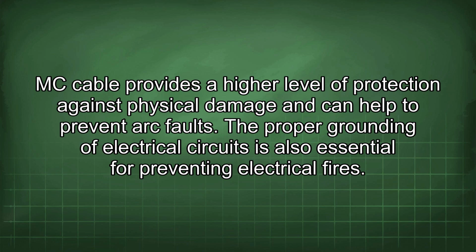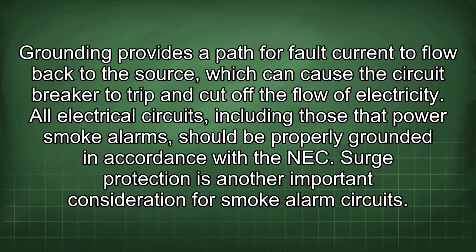The proper grounding of electrical circuits is also essential for preventing electrical fires. Grounding provides a path for fault current to flow back to the source, which can cause the circuit breaker to trip and cut off the flow of electricity. All electrical circuits, including those that power smoke alarms, should be properly grounded in accordance with the NEC.